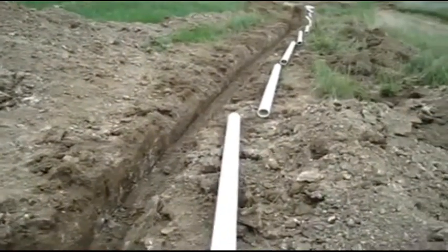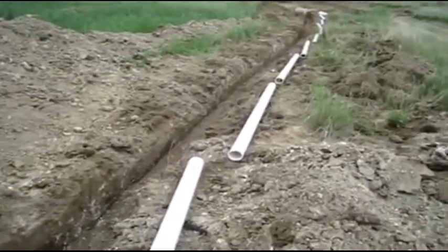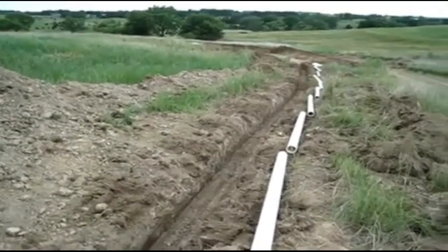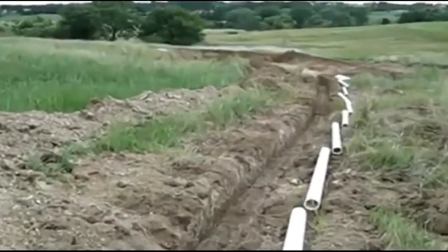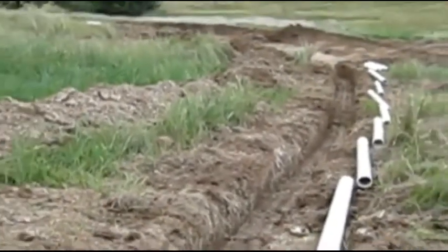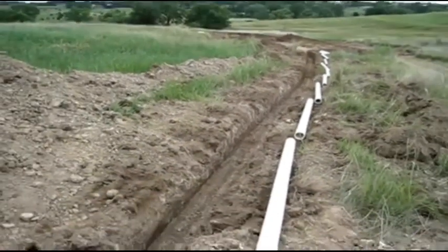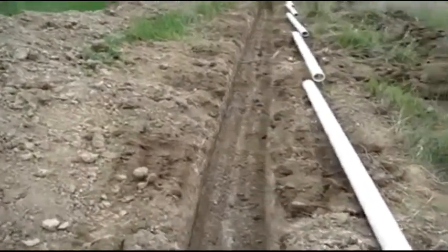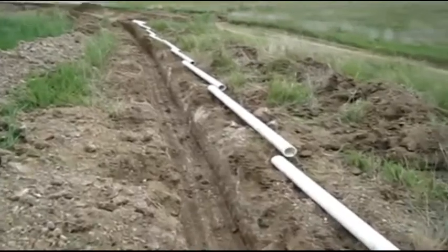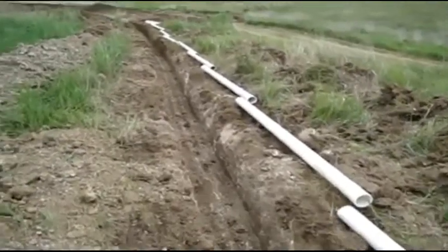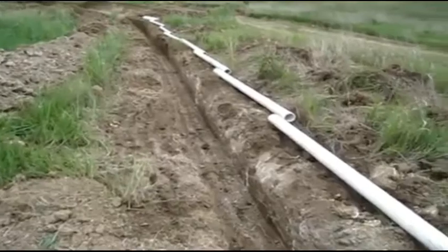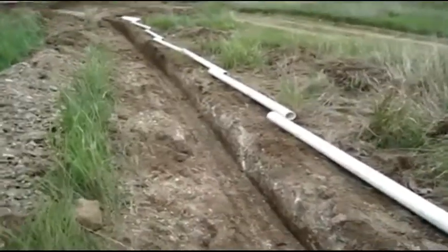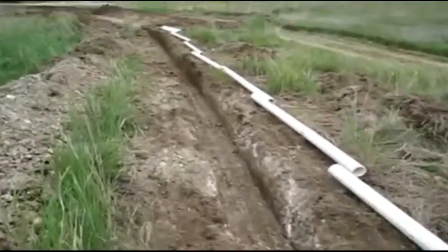nutrients. The wetland cell typically consists of an impermeable liner and gravel along with the appropriate wetland plants, which must be available or be able to survive in a perpetually saturated environment. A wetland system can work via either gravity flow or pressure distribution. As wastewater flows through the wetland, it may exit the wetland and flow into a drain field for further wastewater treatment into the soil.